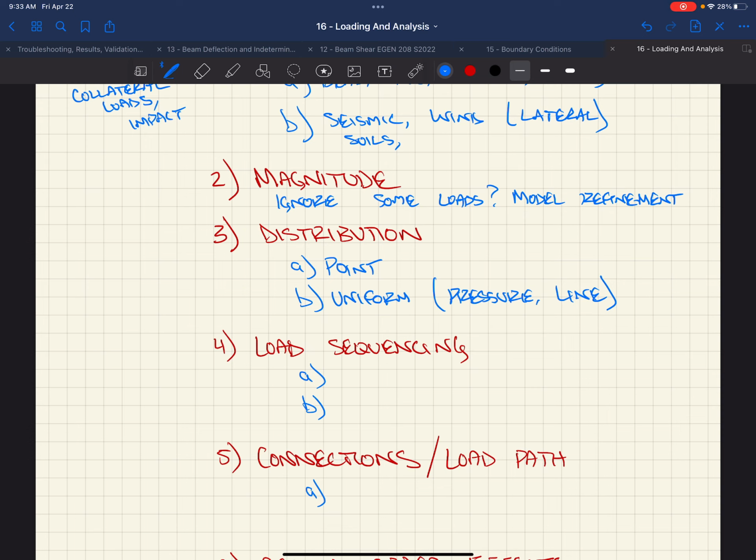Yeah, sometimes you could. Like, sure. Anything we've done in school has been ignore all stiffness out of plane of shear walls, count on everything that's in that direction. Yes, I would say that if you were designing that individual shear wall, like an exterior wall, you would look at it that way. But if you were looking globally at the entire building and what's going on, I would probably do a line load and do an analysis ignoring some of that local behavior and local forces. And then at the end, when I went to design that actual wall, I'd start thinking, okay, what other loads are on this that I ignored when I created this analysis in the first place, that I should probably put on this now.